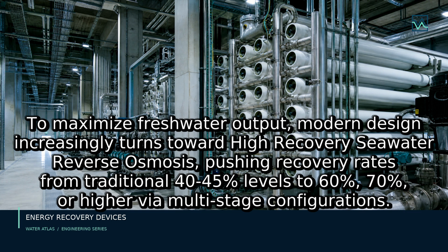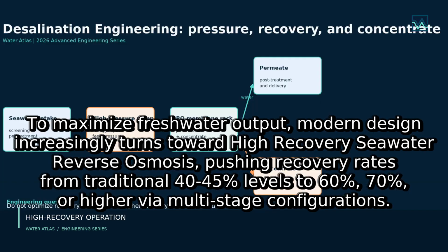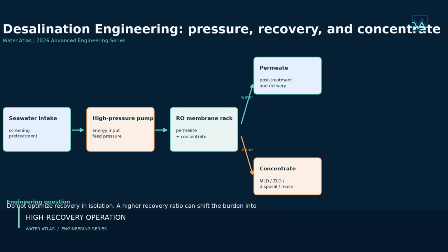For coastal facilities, traditional brine disposal relies on engineered outfalls with multi-port diffusers designed for rapid initial dilution within permitted mixing zones. However, in enclosed water bodies, inland desalination plants, or strict environmental jurisdictions, ocean disposal is restricted or prohibited. This has elevated the importance of minimal liquid discharge, or MLD, and zero liquid discharge, or ZLD, technologies.